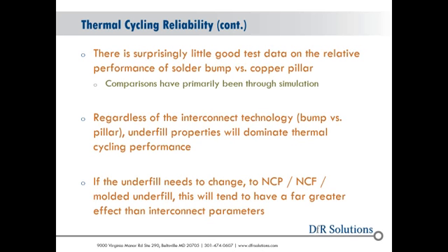And one of the things we've been talking about just very recently here at DFR is to take that physics of failure concept and apply it to every aspect of electronics. Ask the questions. If you ask the right questions, you get the right answers. The question we're asking here, that we don't always unfortunately see in the supply chain, is what happens in terms of underfill when I change the interconnect structure? I think, at least here at DFR, there's some uncertainty as to how well that mitigation from the underfill will be present and whether you can accurately capture the mitigation effect during simulation.